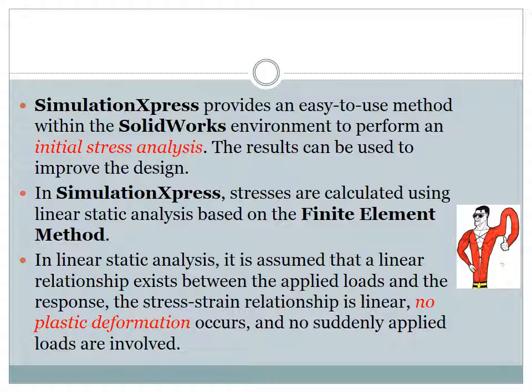In Simulation Xpress, stresses are calculated using linear static analysis based on the finite element method. In linear static analysis, it is assumed that a linear relationship exists between the applied loads and the response. The stress-strain relationship is linear, no plastic deformation occurs, and no suddenly applied loads are involved, which of course is not true in the real world, hence why this is used primarily for initial stress analysis.